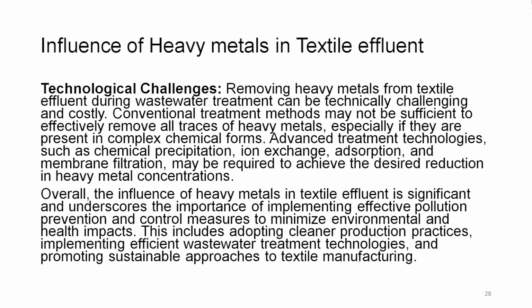Technological challenges. Removing heavy metals from textile effluent during wastewater treatment can be technically challenging and costly. Conventional treatment methods may not be sufficient to effectively remove all traces of heavy metals, especially if they are present in complex chemical forms. Advanced treatment technologies such as chemical precipitation, ion exchange, adsorption and membrane filtration may be required to achieve the desired reduction in heavy metal concentrations.